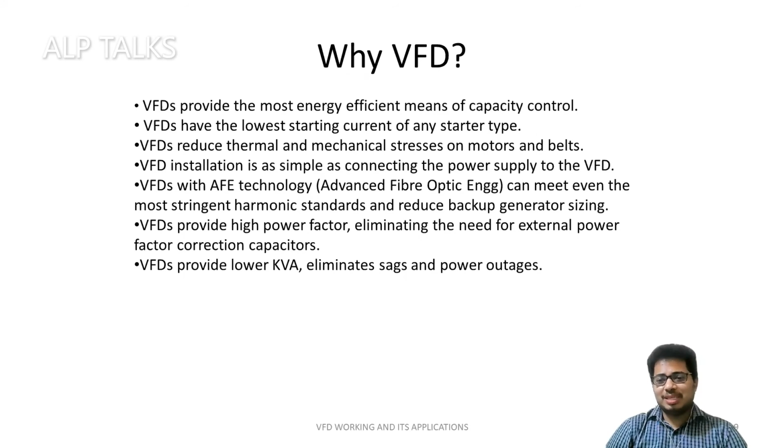So why do we need this variable frequency drive? Now, whatever we discussed till now is about the operation, how the circuit will be, how we are doing. Now, why VFD? VFDs provide the most energy efficient means of capacity control. VFDs have the lowest starting current of any starter type. VFDs reduce thermal and mechanical stress on the motor and belt. This is one of the most important things we have to keep in mind.